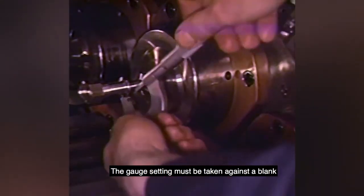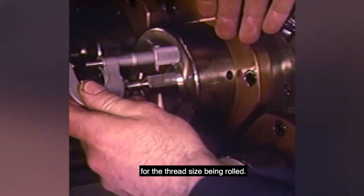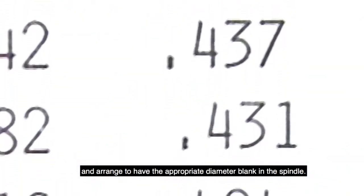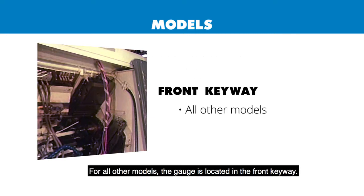The gauge setting must be taken against a blank that has been shaved to the correct diameter for the thread size being rolled. Therefore, locate your specific thread size in the thread rolling capacity and reference data charts and arrange to have the appropriate diameter blank in the spindle. Advance the cross-slide to the full forward position. For attachment models 141, 142, 145, 151, and 152, the gauge is located in the rear keyway. For all other models, the gauge is located in the front keyway.